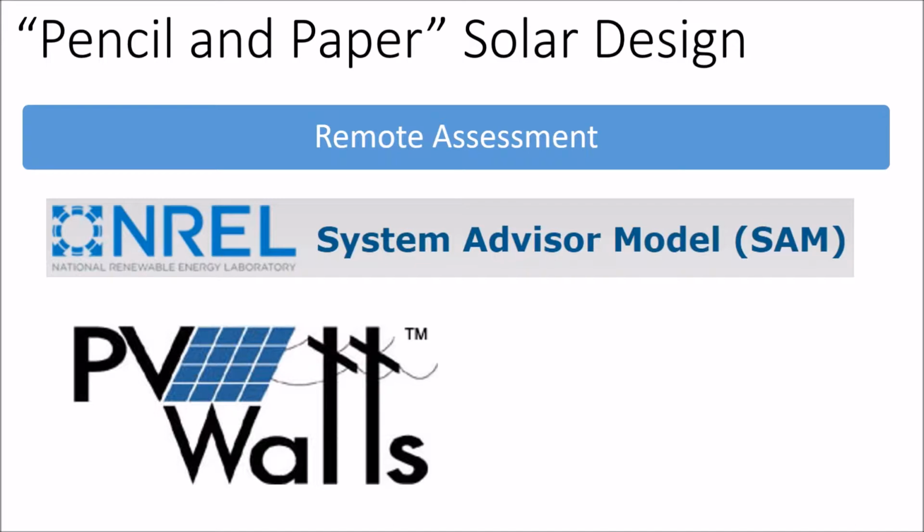With PV Watts, you can't open up the module spec sheet and hard program the temperature coefficients. It assumes a temperature degradation that's actually about 15% too aggressive compared to the standard module types. And it's not like that's completely inflexible. Within the PV Watts input, you can select between a standard module, a premium module, and a thin film module. And if you read the documentation, that's toggling those temperature coefficients. So you can pick the best fit within PV Watts.